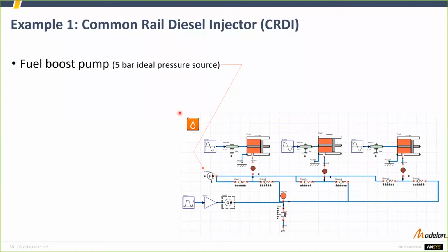So we have, of course, the oil component here. The oil, which is dragged and dropped at top level, applies to all hydraulic components inside. So all the properties in each of these components refer to this oil defined here. If you want to change oil, you just have either to select a new oil in this component, or to drag and drop another oil.